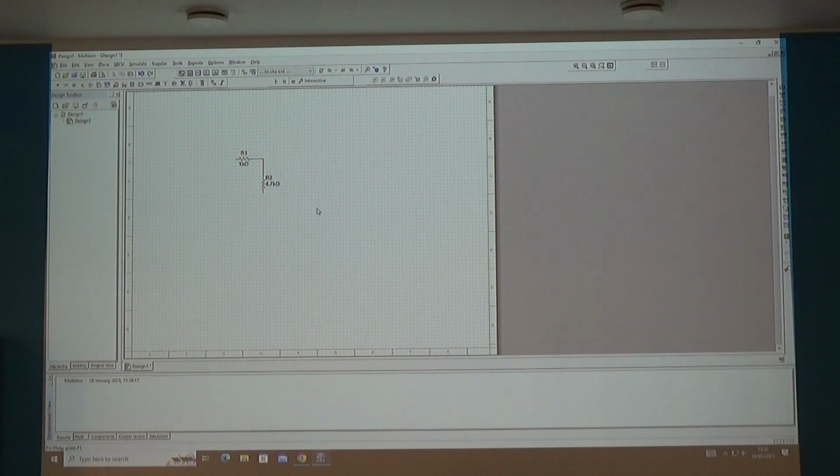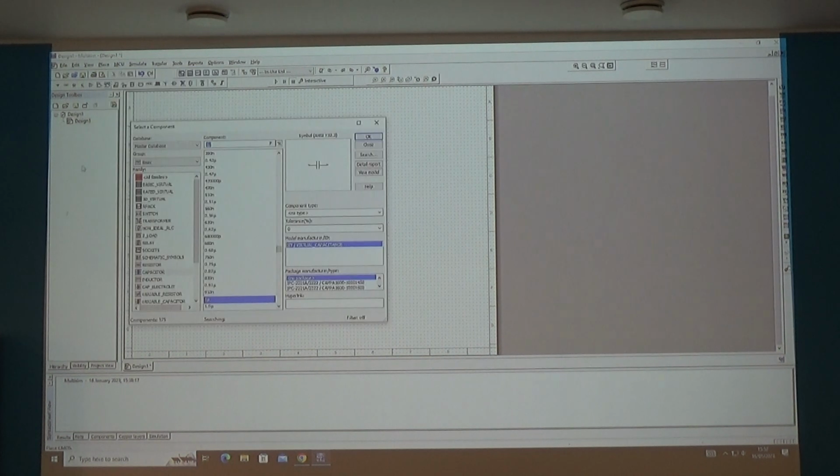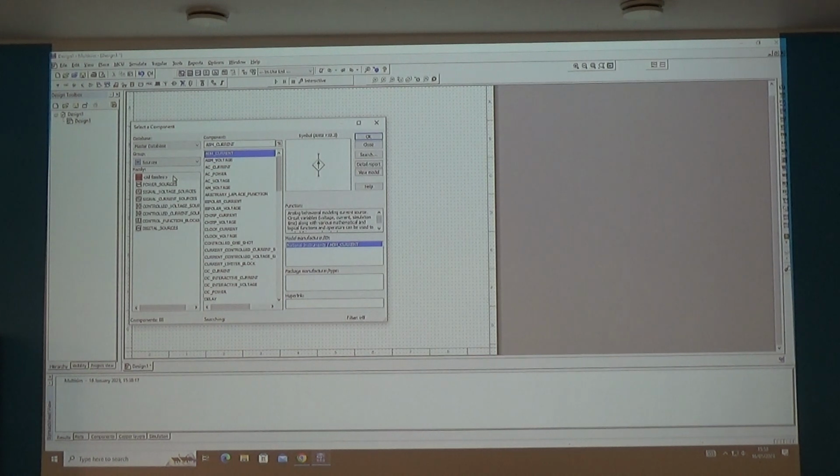So what else do you think we need for a circuit? What is invaluable in an electronic circuit? Power supply. A power supply, well done sir. So from over there, you head down there, look. So you need a power supply. Well, what does a power supply look like inside Multisim? Well, let's have a look in here. So let's do Place, Component, and let's have a look down this list here. So what do you reckon it is, Mike? Do you reckon it's Sources, the top one? I reckon it's the top one. So we go into Sources, and look what we have there.